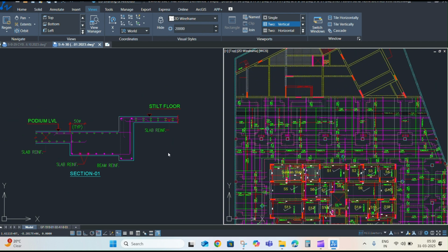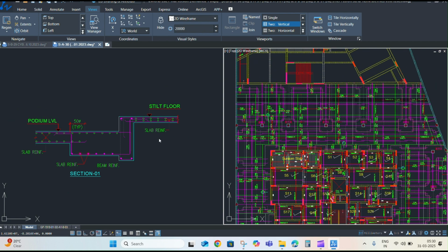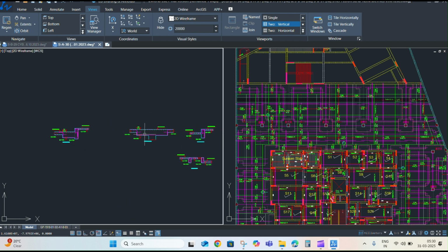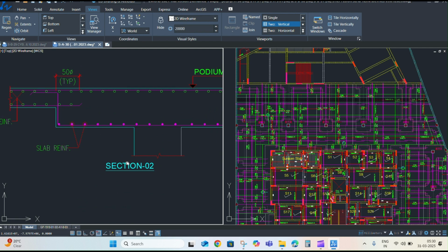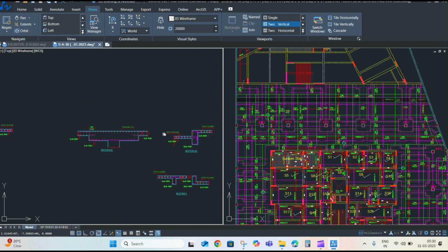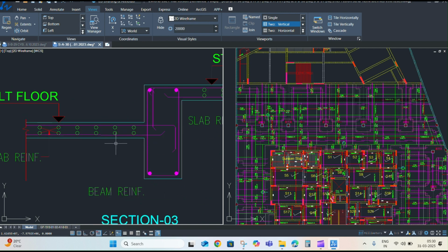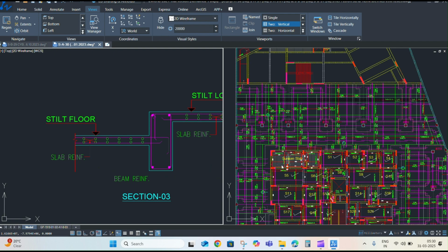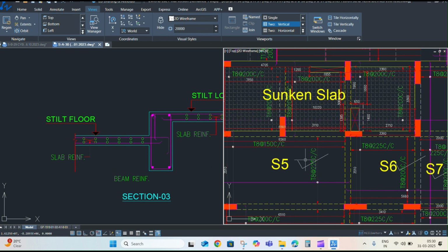Common bar bending shapes. Straight bar, no bends, used for straight reinforcement. 90-degree bend, used for anchor points or where the bar needs to turn. 135-degree bend, a more gradual bend for anchoring or turning reinforcement. Hooks, used at the ends of bars for anchoring them in concrete.